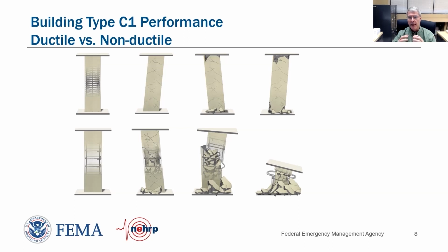And then our non-ductile column, since we're removing or blowing out that concrete between the confines of our steel reinforcement for the column, that's taking all of our compression loads or gravity forces. And so our column loses all bearing strength, and it's trying to support the building above it, and it just collapses. And that's what's illustrated in the non-ductile column below.